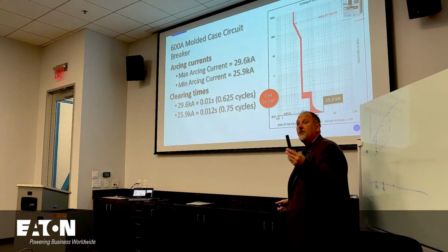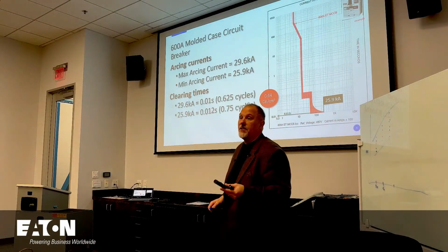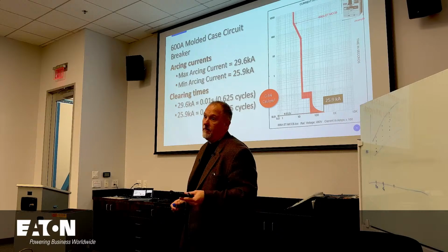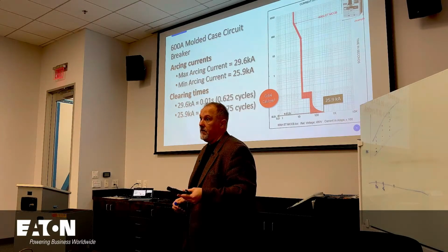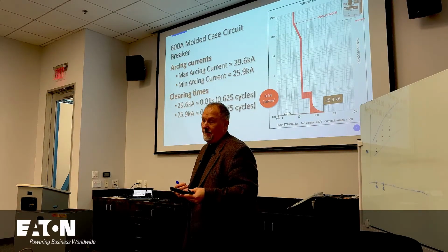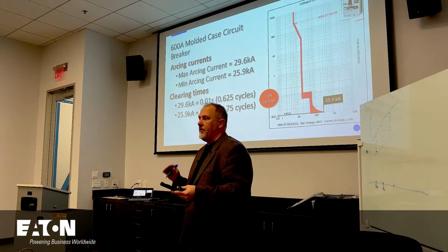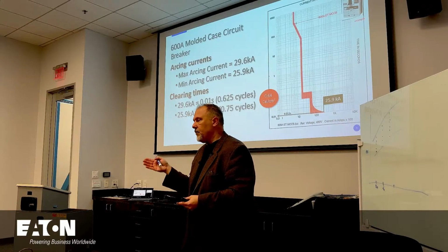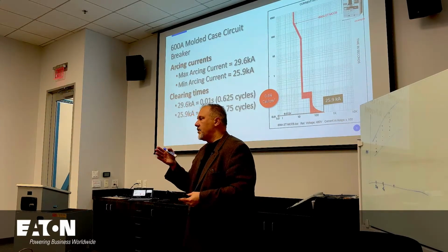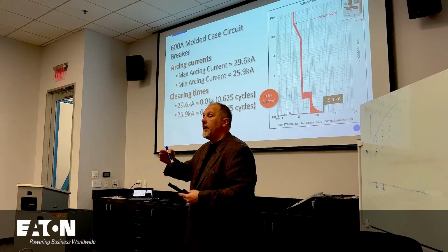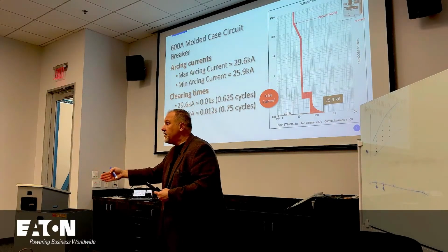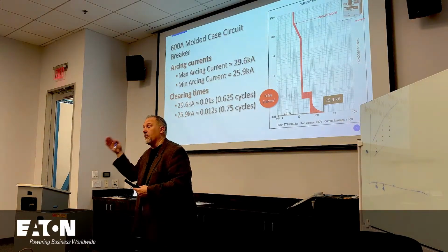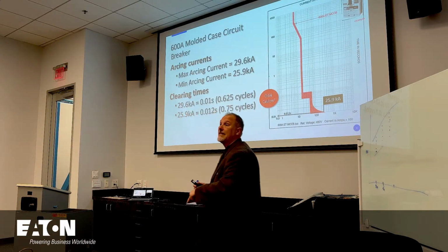Now, 240.87 and 240.67 have us do a comparison with arcing current, but it doesn't say whether you're doing the maximum or the minimum. In my humble opinion, I would say the minimum would be your worst case, because what you're looking at in 240.87 and 240.67 is whether or not you are operating the arc reduction maintenance switch or operating instantaneous or any of the technologies that are recognized in those sections.